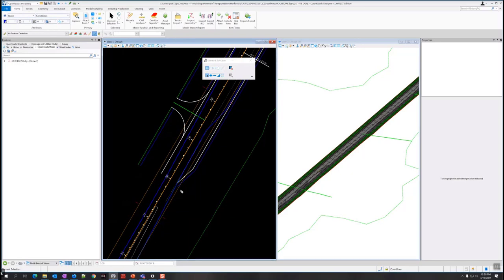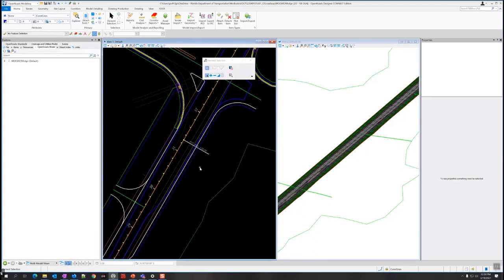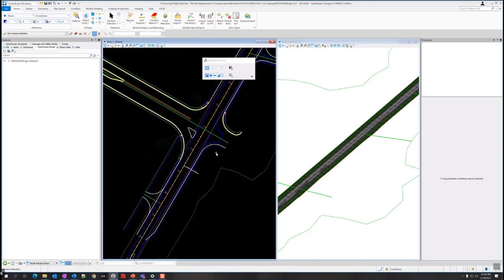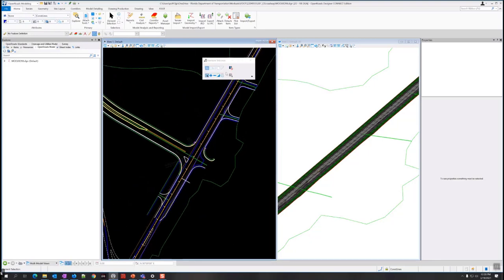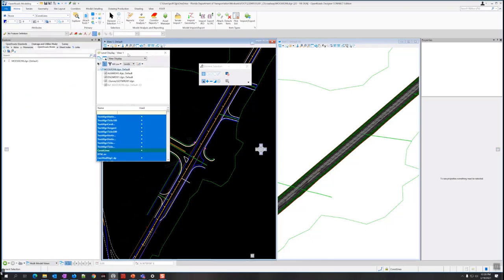So these have feature definitions, and we need the pavement asphalt UPA, that's for widening, and the paved shoulder, so I can get the shoulder width accurate. So basically we want to reference all those lines in to this corridor. So we need to create a selection set of those. So without using that command, the best thing is just going to be go into your level display manager here.